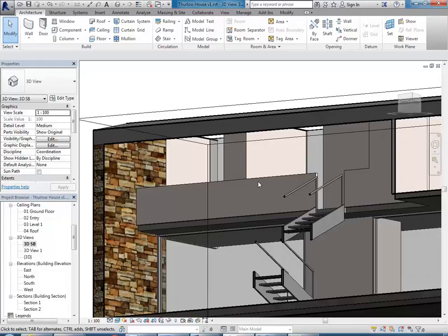Right above that, about next panel up. Yep, there, that's it. So scroll down a little bit there. I think I can actually see it just at the bottom there. It is section box. You're going past it. So just on the left, you'll see section box. Just tick that box, and then you'll get a box come up in your view. Press apply if it doesn't come up straight away, and then you can select that to get the arrows.